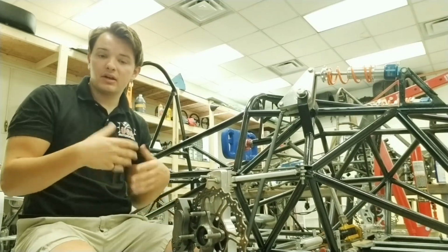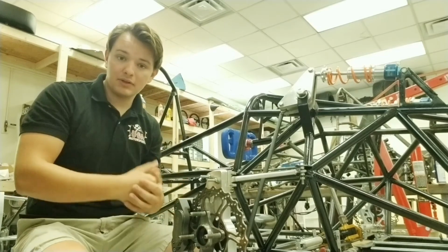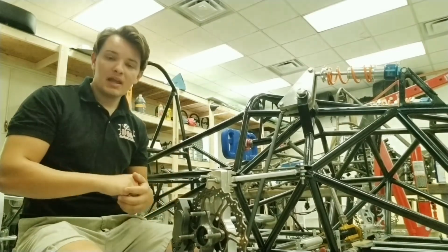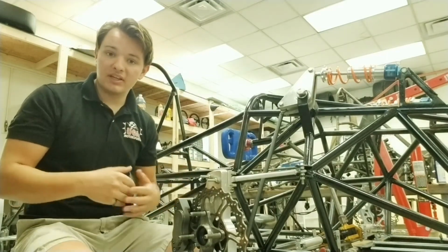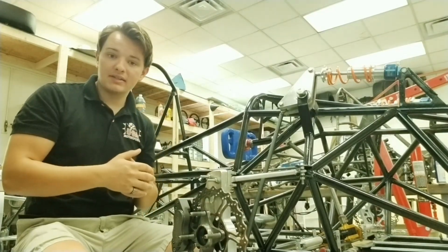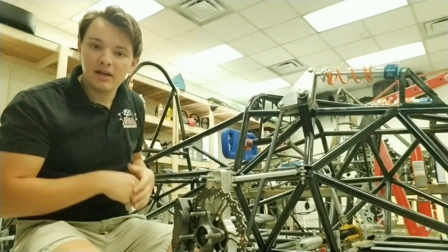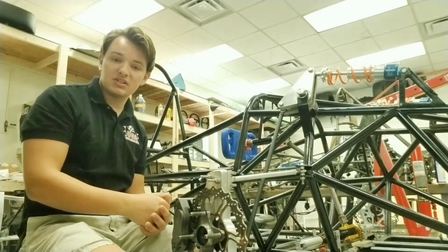Once I had talked to all the members, I created error bounds for the weight and center of gravity location for each component. Adding all of these together created what we expected to be the total weight maximum and minimum, as well as the range of where the center of gravity might lie within the vehicle. And these values were used to design the other suspension system components.